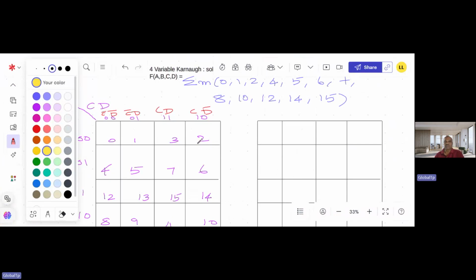And one more technical question is why these numbers are reversed. In the previous video, I explained clearly. Actually 0, 1, this is not 3, this is 2 only, but it is transformed into a different representation. That is, 2 is written as 3. That is called the gray coding technique. So here we are using the gray coding technique. So the question is, in a Karnaugh map we are using a different form of representation, and they may ask you to write it as gray code. Since 0, 1 is the original form, 3 and 2 are the gray coding form of representation. In that, 2 is written as 3 and 3 is represented as 2.